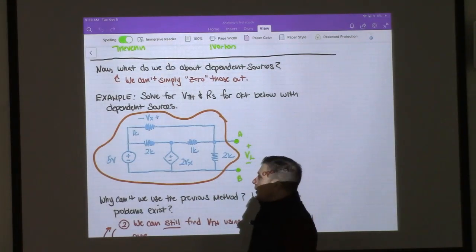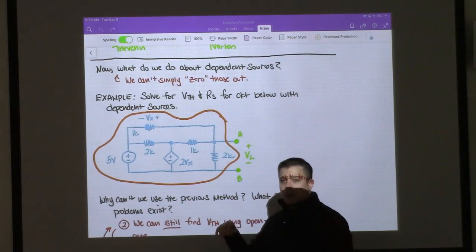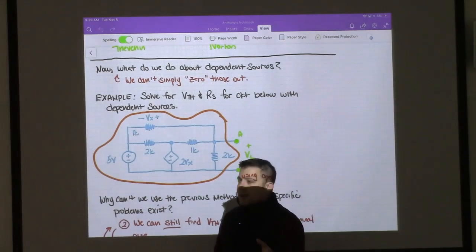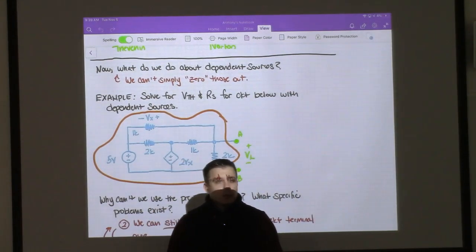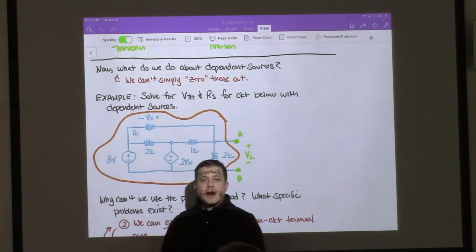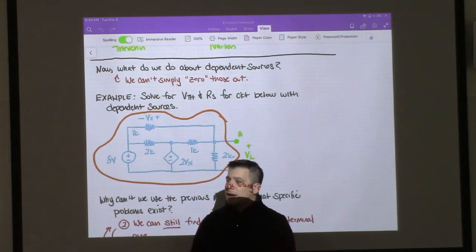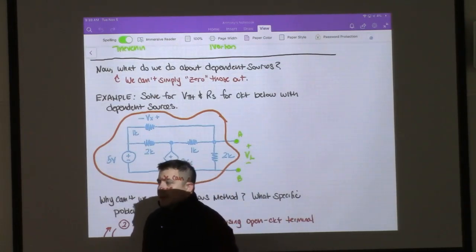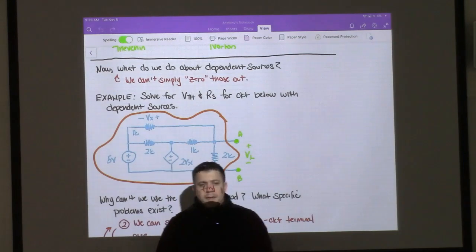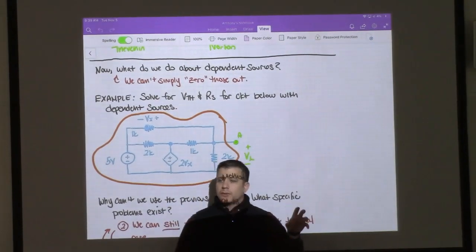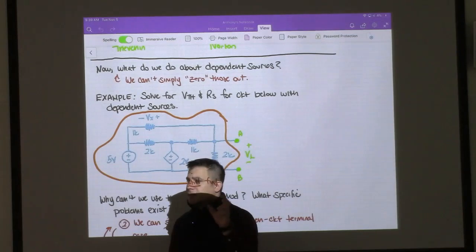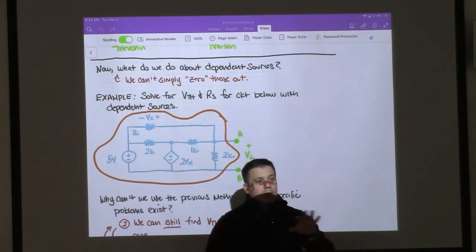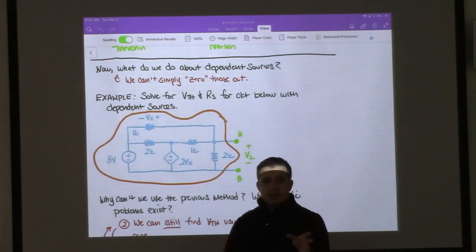All right. So what I'm going to do is start from here. We'll talk about what the first couple steps are, and then we'll finish it off. Taking a second to review what we have done: Chapter 5 is about Thevenin and Norton equivalent circuits, which you can also call equivalent sources. They're equivalent to one another, right? Thevenin is composed of an internal voltage with a series resistor. The Norton is an internal current with a parallel resistance. We know that we can switch back and forth between those two, which is an interesting characteristic.